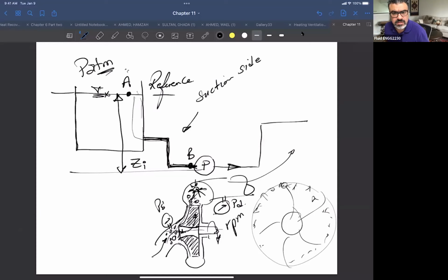Negative value here in this case, because if you're looking at, I don't know if Cedar, this is what you meant by vacuum in terms of the vapor pressure itself. Yes, if the vapor pressure is given as a negative value, that is actually given in the gauge term, right? Because gauge means that atmospheric is 0, lower than atmospheric is vacuum, higher than it's plus, or positive.